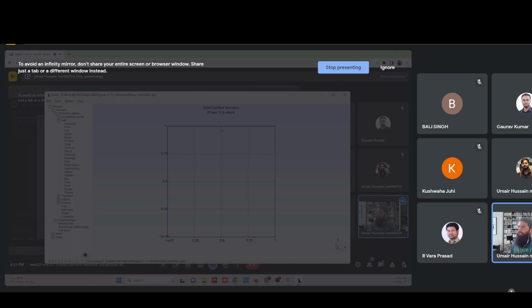You see these symbols, these arrows coming up here. That means this is now a surface. Next, you have your domain ready now. If you want, you can also add physical identity to these different boundaries. For applying boundary conditions, this is essential in your code. Anyways, we don't need it now, so we just create a mesh. You see, a mesh is created, four triangles here.